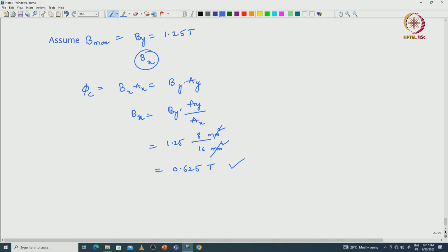The next question asked in the problem is the equivalent circuit. In the equivalent circuit, the source will be MMF, our effort variable is MMF, and the flow variable is d phi by dt. Flow and effort variables are defined with respect to the gyrator principles. Next we have to draw the capacitors, the magnetic capacitances.